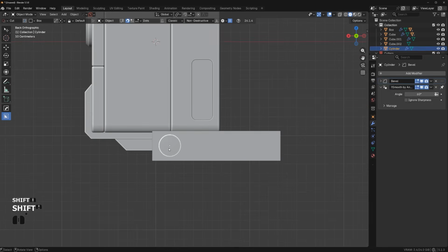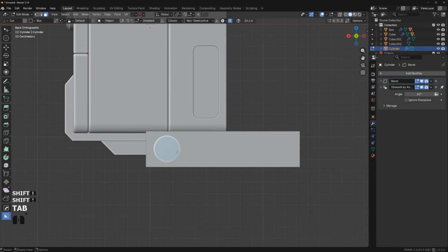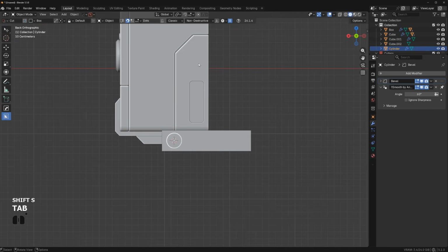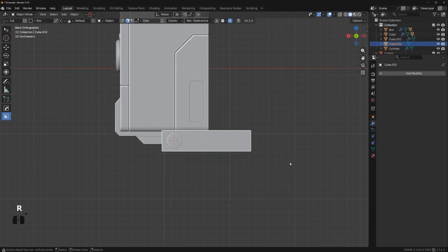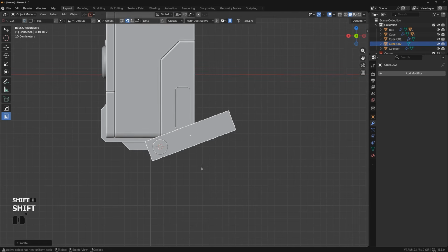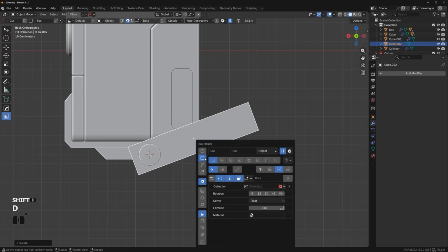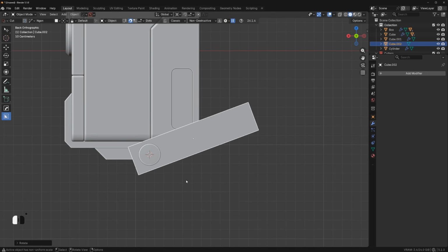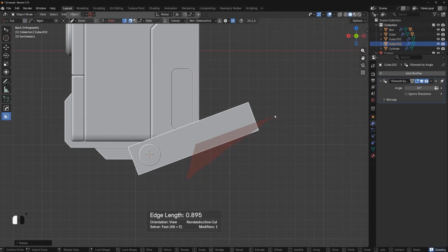We're going to move a cursor here, so we go to face mode, Shift S with machine tools and move cursor to face. And then we're gonna switch pivot to cursor, okay? So we can actually rotate it here on the cursor. So rotate them like this. Let's go to D menu, swap to N-gon and face, and we're going to cut this here like this, okay?